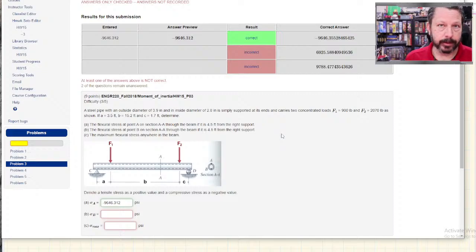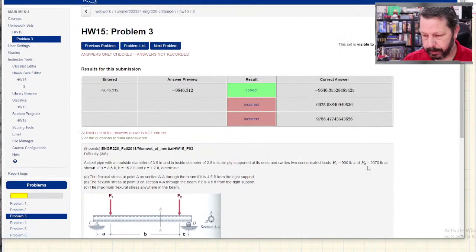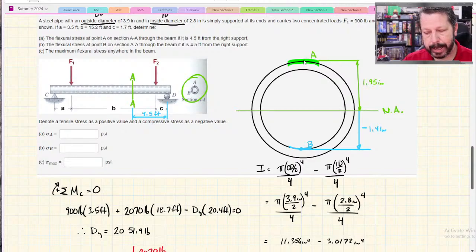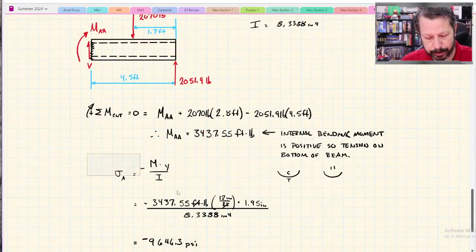And you'll end up with some bending diagram that shows you where the maximum internal bending moment is located. Then you take that one, and as far as, do you use point A or B, you would use point A, either at the top or all the way at the bottom of the beam, because you want the maximum worst case number that this equation would generate.